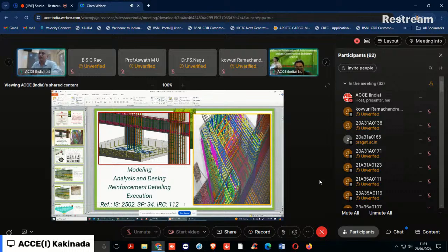The bottom is vertical permeability. From the horizontal side, it is horizontal permeability. We have to consider the permeability of the concrete both in the vertical direction and the horizontal direction. Similar to soil, there is a distinction between horizontal permeability and vertical permeability. We generally distinguish soil permeability as 10 to 1,000 times higher for horizontal permeability when compared to vertical permeability. Similarly, we keep in mind this variation in the permeability of concrete in the vertical and horizontal directions.